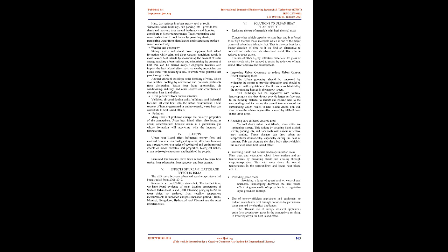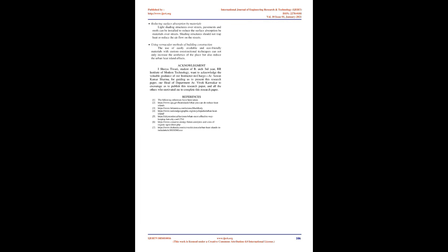Solutions to urban heat island effect. Reducing the use of materials with high thermal mass. Concrete has a high capacity to store heat and is referred to as high thermal mass material, which is one of the major causes of urban heat island effect.